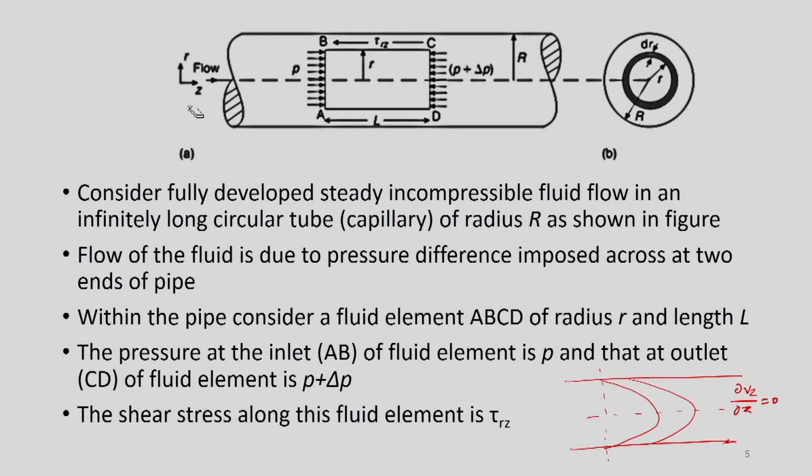Now, we need to do a momentum balance for this system, and then develop the respective equations which we need in order to ascertain the rheology of the fluid. So, we make an assumption that there is only laminar, steady, incompressible flow under fully developed flow conditions.